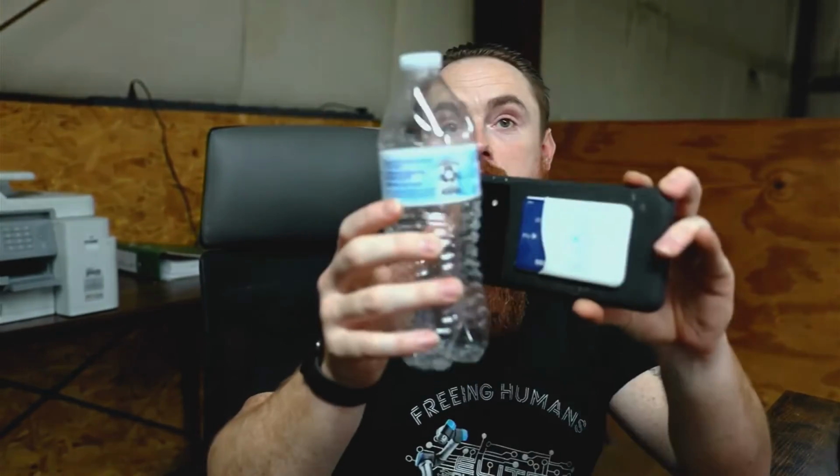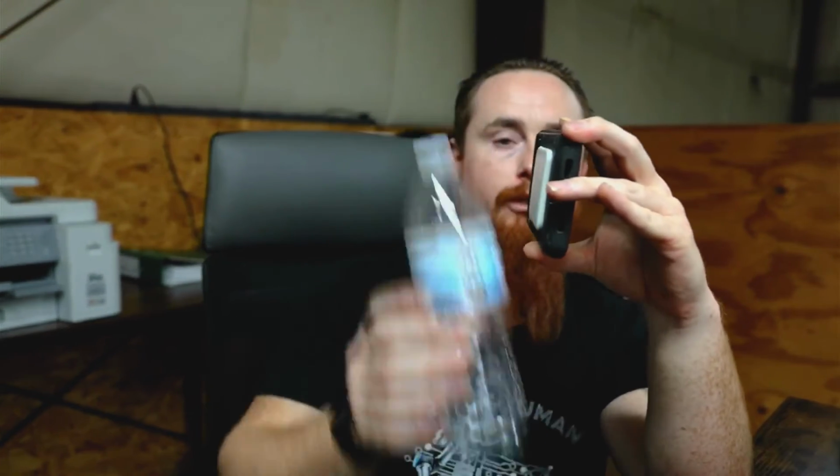The next big thing to keep in mind is that when you're doing a joint move, the arcing will be larger based on the speed of the robot. The faster you move the robot, the bigger the arc will be. If you said move at 10% speed, maybe the robot just arcs like this, and maybe it looks very linear. But you bump it up to 50%, and it's going to go like this. You bump it up to 75%, it's going to go like this. You bump it up to 100%, it's going to go like this. Joint speed will go from this point to this point as quick as it can.